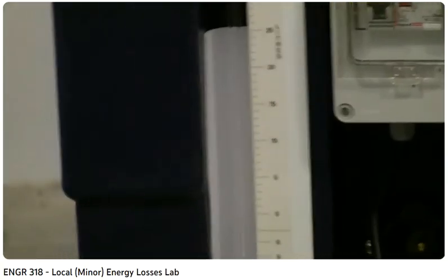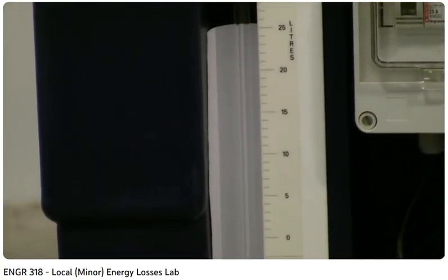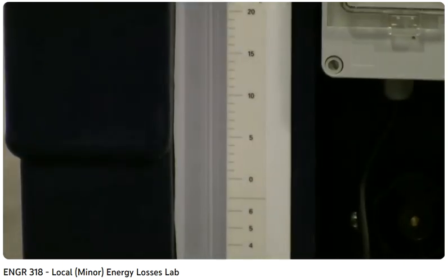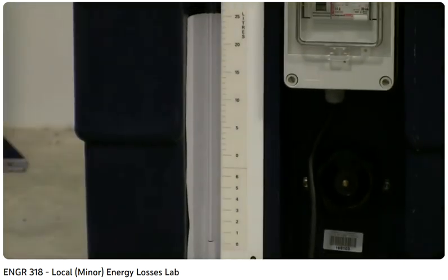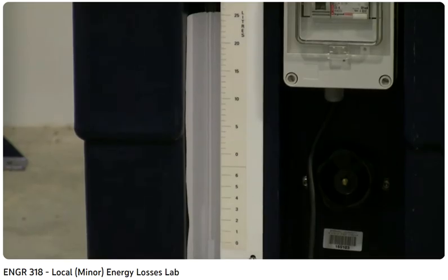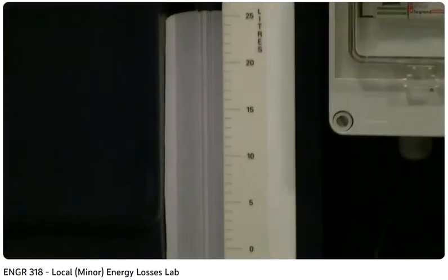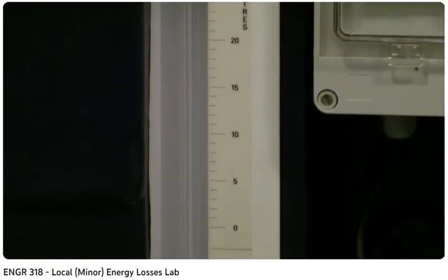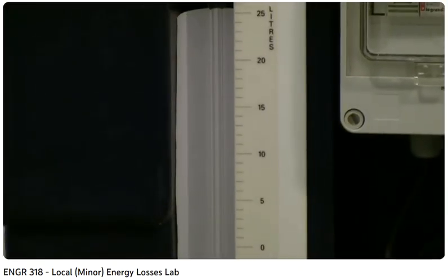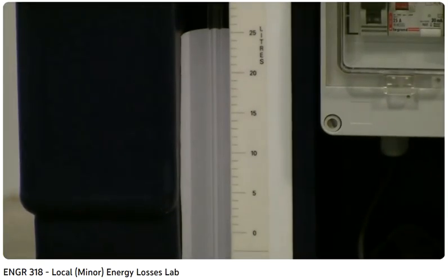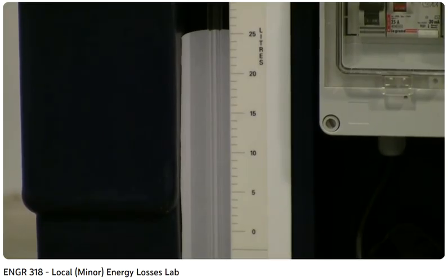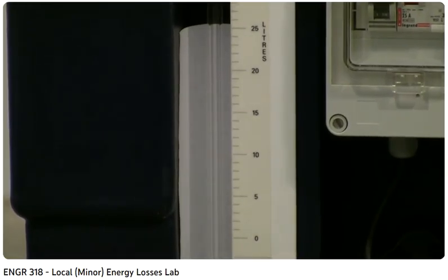Now, when I drop the ball inside of the wet well, it's going to allow water to begin accumulating. You'll see it on screen. It's going to first go through these slow flow rate graduations of 0 to 6 liters, but you will note the time that it passes the 0 mark on screen, and then you're going to measure how long it takes to accumulate 25 liters inside of the wet well. So I'll go drop the ball on that now. You should have a stopwatch handy, some sort of a way of measuring the time, hopefully more precise than just looking at the time counter on the screen as you're watching this video.